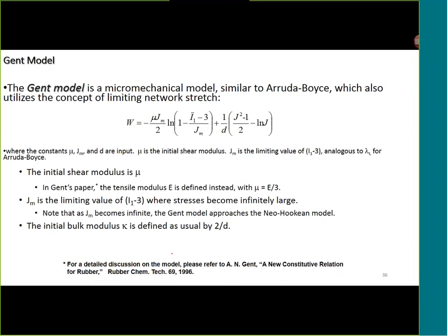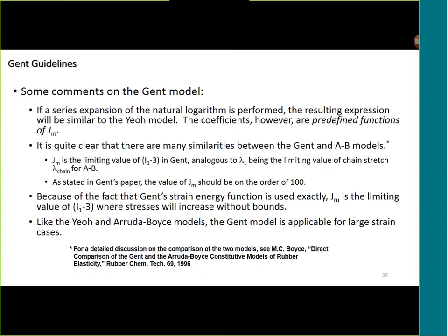The Gent model is another micromechanical based model which is similar to Arruda-Boyce, but there is a difference in the limiting value, at what limiting stretch value your stress stiffening is picking up. Here are some guidelines for the Gent model.